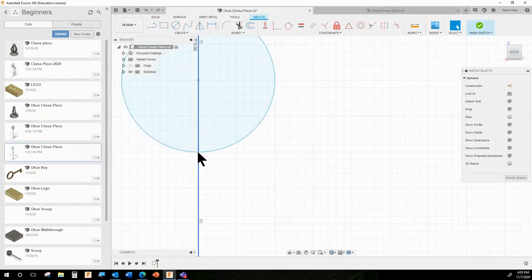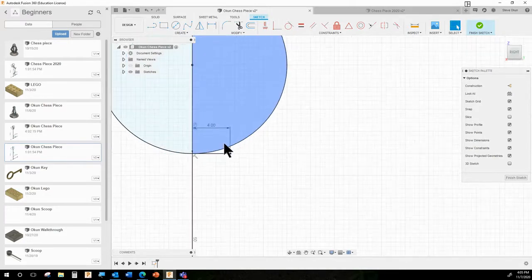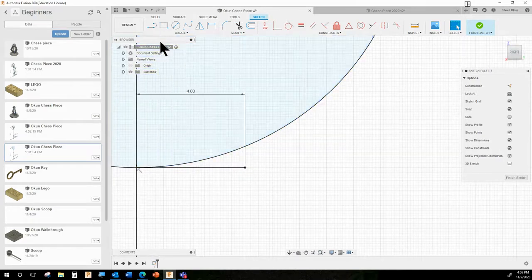Okay, so they've told me that the line is going to end at the head 4 millimeters from the central axis. So once again, I'm going to draw a pair of construction lines. I'm going to go out 4 millimeters. So I'm just going to start the line out and then type in 4. Wish you could see my keyboard. And then I'll zoom in even a little more here so you can really see what I'm doing.